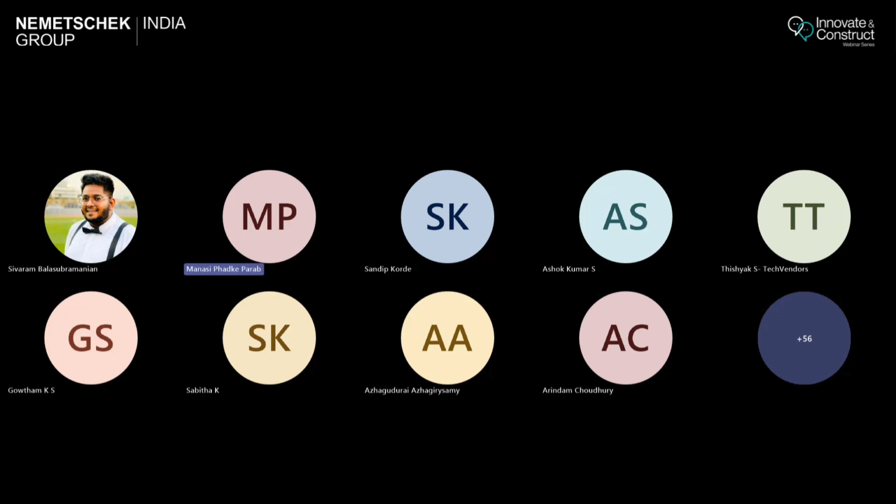And lastly, we also saw some quantification. If I have my DSR codes, can I add them? Let's say 001 is the DSR code for concrete. Can I get all these concrete quantities in one column and quantify those, like 50 cubic meters or 60 cubic meters of concrete for M20, M40 concrete, likewise, or let's say D1 type of doors, all doors listed from the entire project onto that particular item?